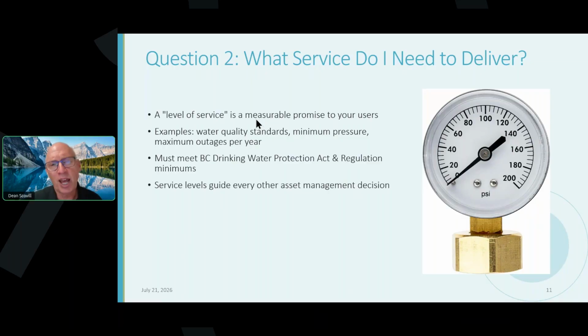The field staff said to the engineering staff, I think we better do this really slowly instead of just going from, say, 30 psi to 40 psi, because people have old service connections, old plumbing. And the engineer said, oh no, we're okay. We should be able to go right to 40 psi.